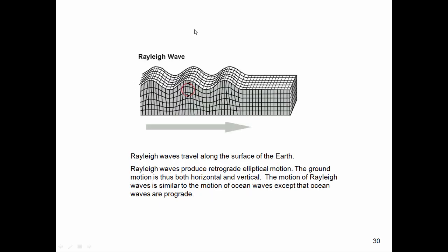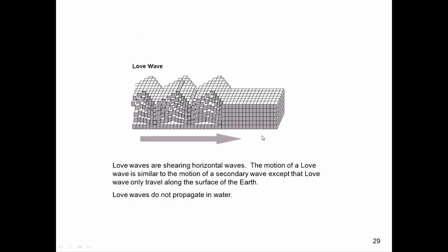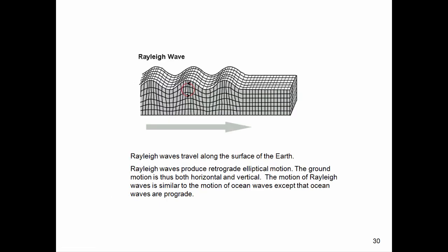Now imagine a tall cantilever beam mounted onto the ground, and a Rayleigh wave comes along. Well, that's going to cause that tall cantilever beam to have a vibration that's in plane with this slide. So it's the Love wave and the Rayleigh wave that are of most concern to earthquake engineers.